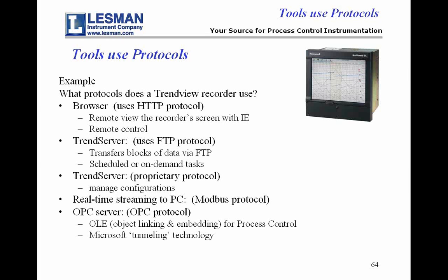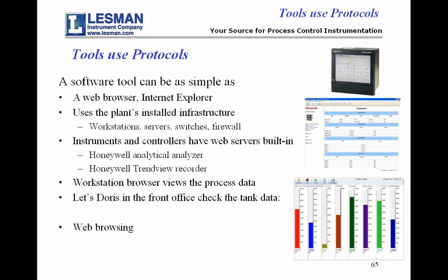And it will also run the OPC protocol, which enables the recorder or the software to transfer data to an OPC client like Wonderware or Scitech or InTouch or RSView or FactoryTalk or any one of those HMI programs that's an OPC client that also needs the data that's on the recorder or on the software package that the recorder runs.